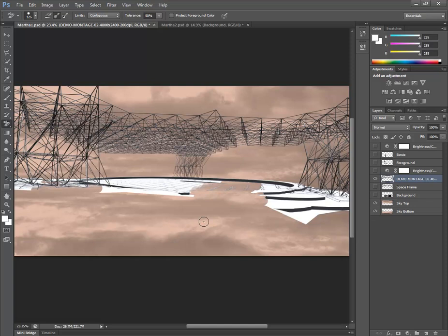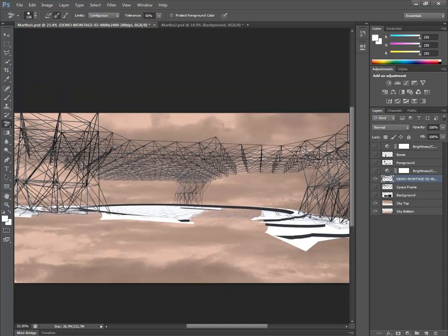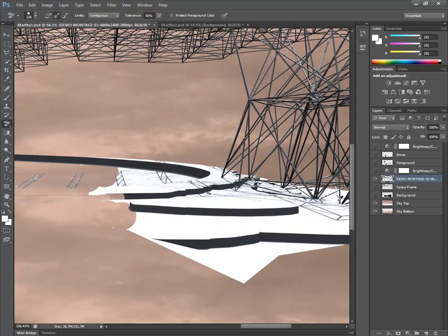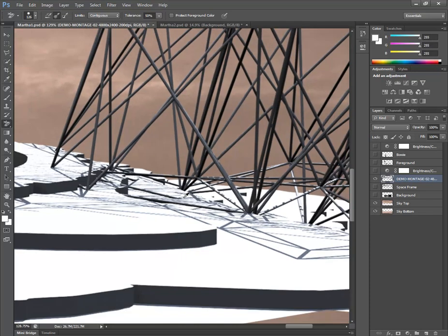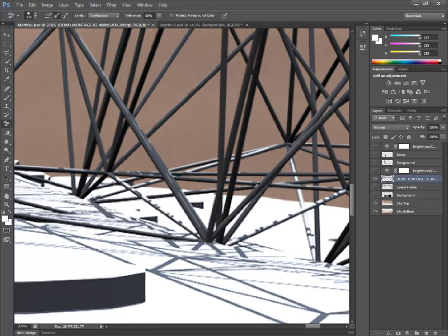That workflow will get you pretty far with this one. You will have some highlights that you want to keep a lookout for once your space frame gets in. You're going to have highlights that are hanging out there, and you don't want to use that tool here, because what will happen is you'll start to delete part of your pipes. So stay away from the pipes with it.